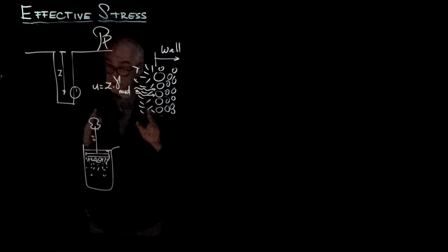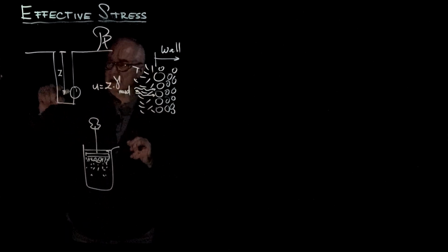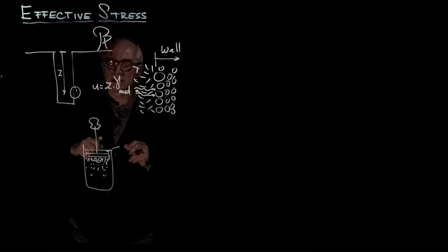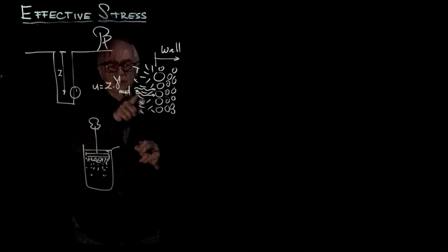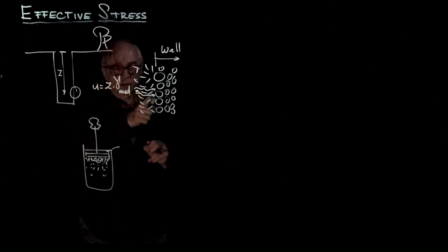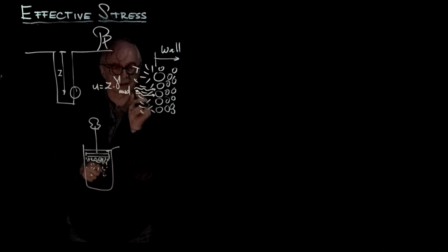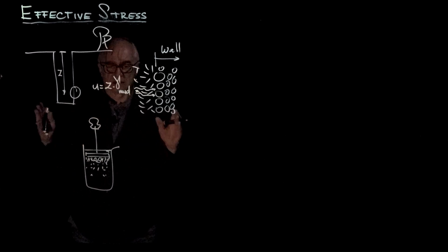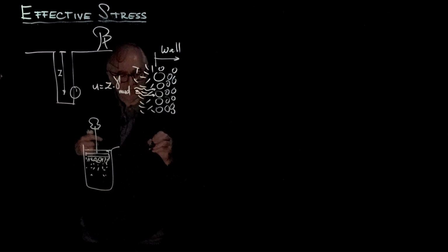And what is so surprising is, imagine that you are 1,000 meters down, and this is 12 kilonewtons per cubic meter. So you are in the order, the fluid pressure here is 12 megapascals. And this goes from zero effective stress to 12 megapascals of effective stress in a very thin layer. Within a few millimeters, there is such an amazing gradient of effective stress. So to magnify this,